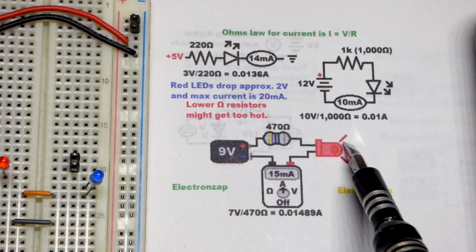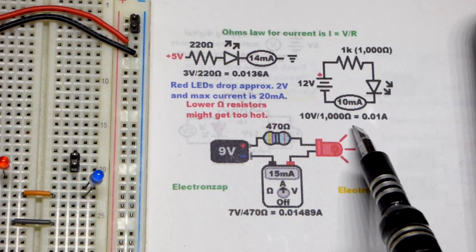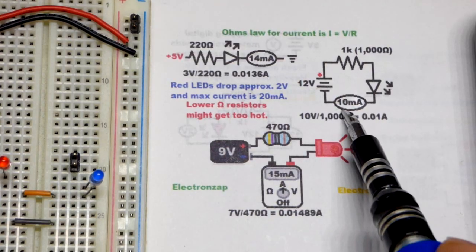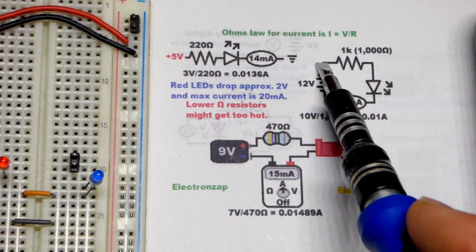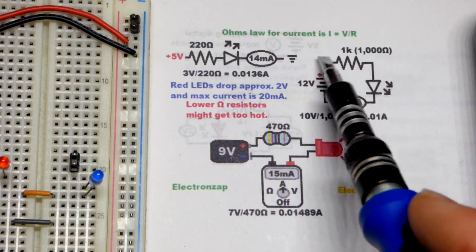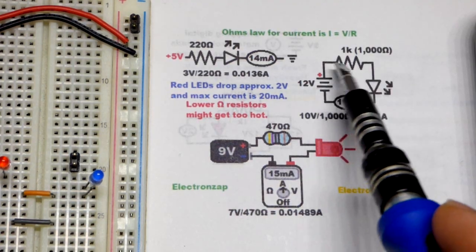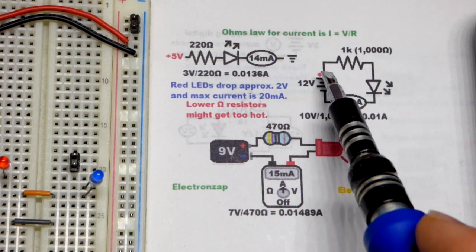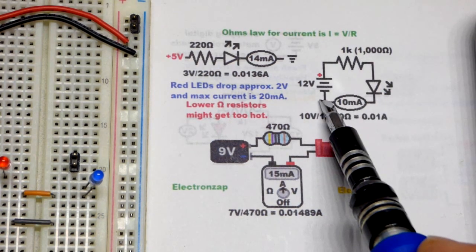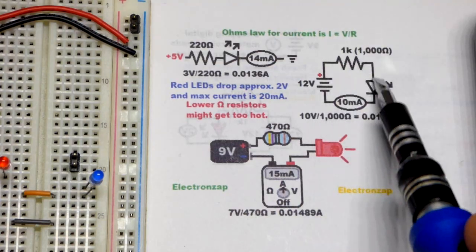You can open up the circuit at this point, bridge the gap, and then measure it like you did here if you want to. You could also open up the circuit there and measure the current. It doesn't matter where you open it up. In a series circuit, when there's just one path for current to flow, it's going to be the same throughout the whole thing. And I'm going positive and negative here.